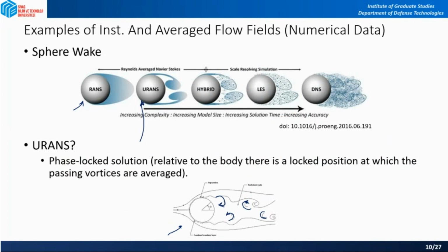So of course, the circular vortex will travel down with time, and we know at another delta t time, the vortex will be perfect circular, but travels down. So the unsteady RANS solution gives you the unsteady or time-dependent motion of the perfect circular vortices, not those very, very tiny ones. You see, these are many vortices in here.